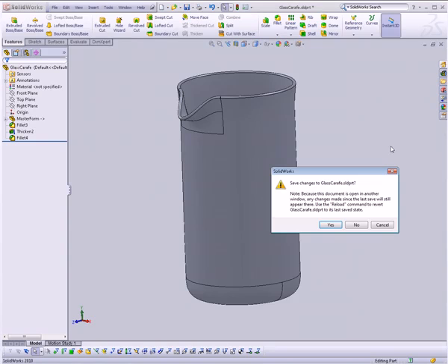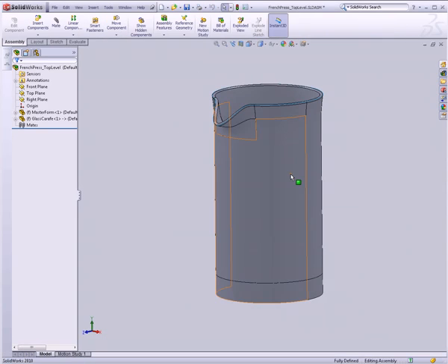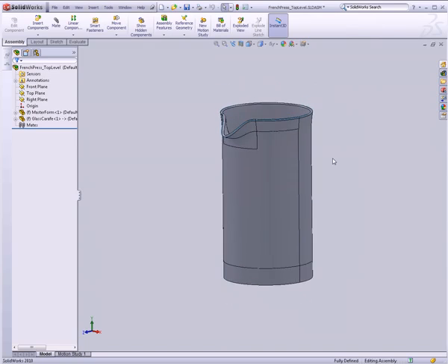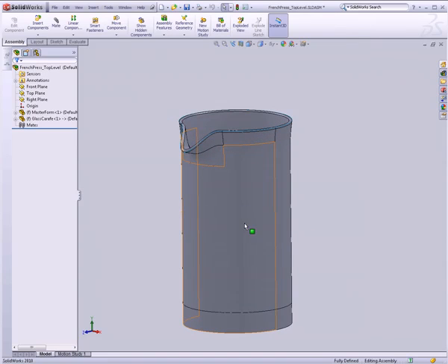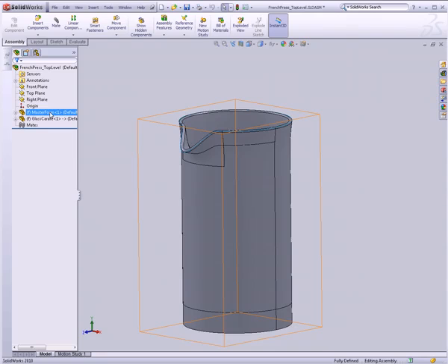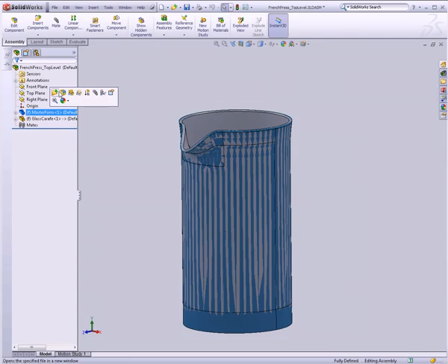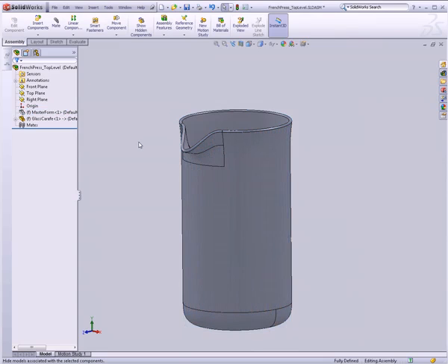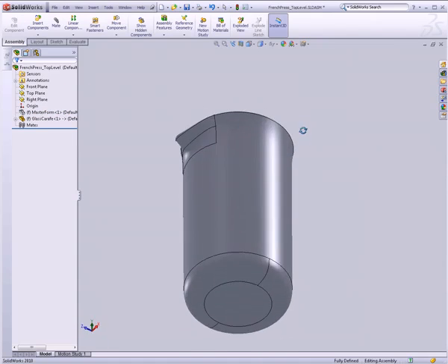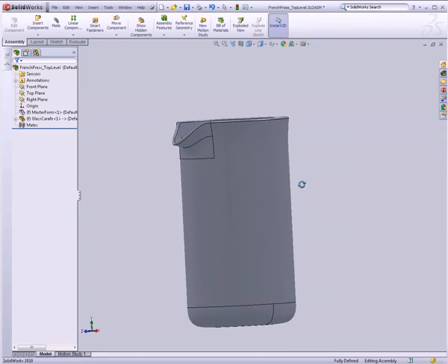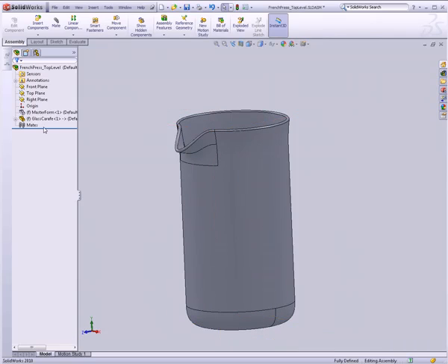Let's close this document, hit yes for save. It's going to take us back to our French press top-level assembly. Now, this looks roughly the same. That's because our master form is showing. Let's click on it, and then up here, there's a Hide Components button. It's got little glasses next to a component icon. And there we go. Now we can see the glass carafe that we created is nicely in place in our assembly, right where we want it.